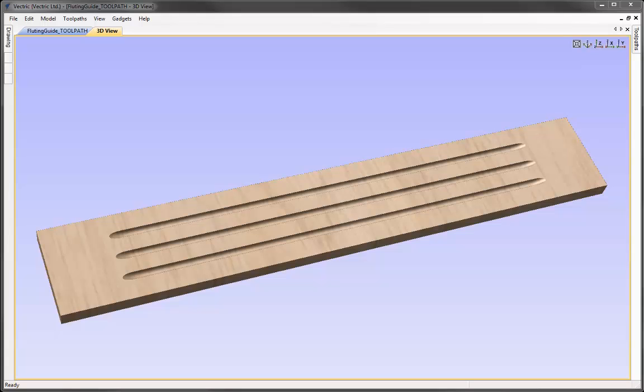In this video we're going to give you an overview of the fluting toolpath and some of the different applications it can be used for. In the first example we're going to show you how to lay out three simple polylines and create the toolpath you can see that would make the part on the screen, this simple kind of column for a mantelpiece.